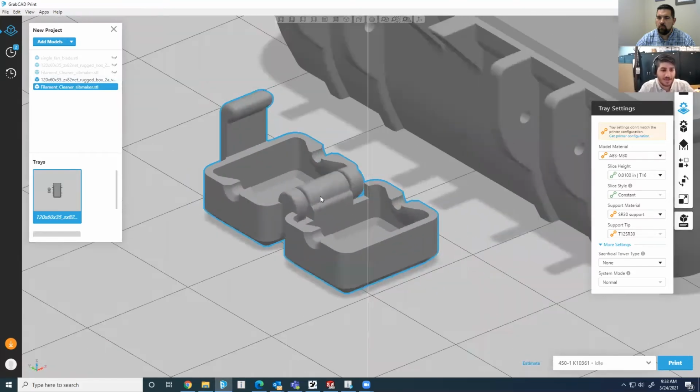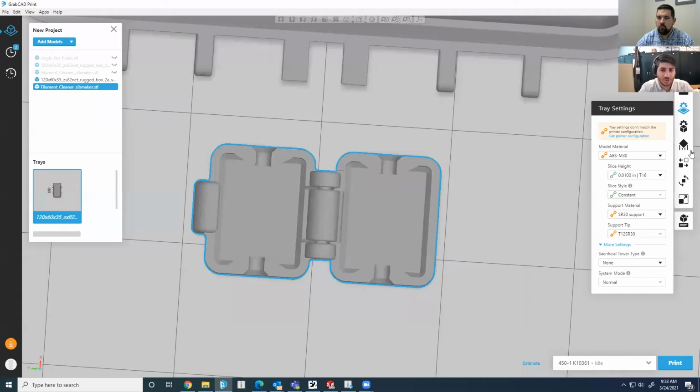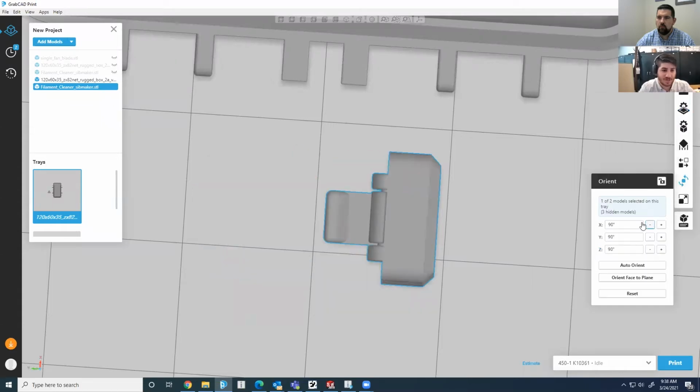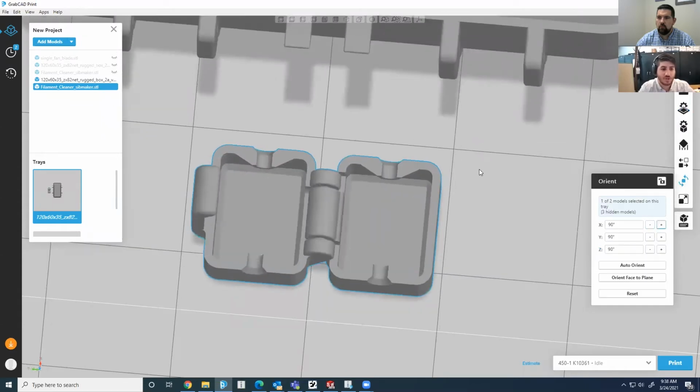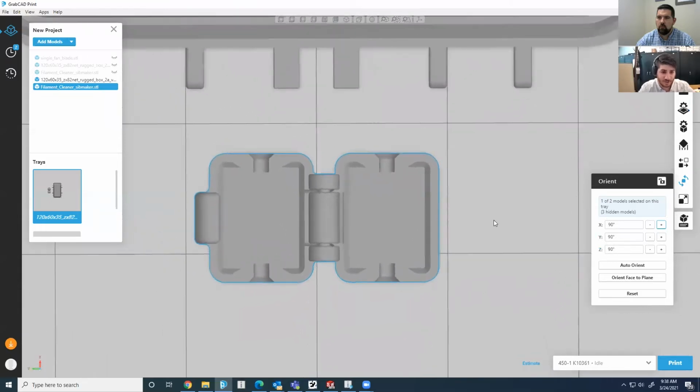And there's a gap between this pin and this enclosure here so that support material, sacrificial support material, can grow inside of that and then dissolve later in our post-processing tank.